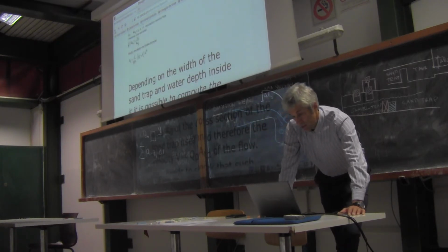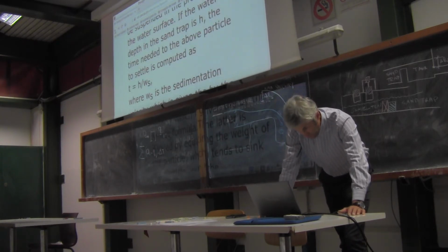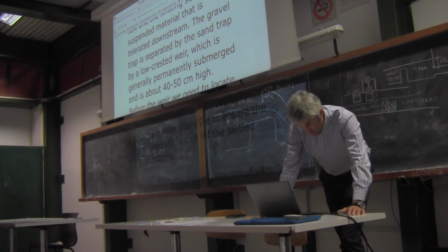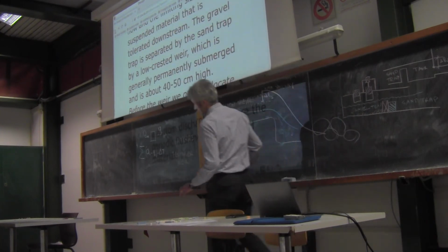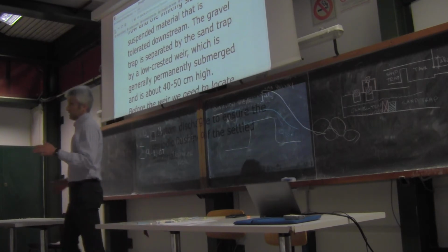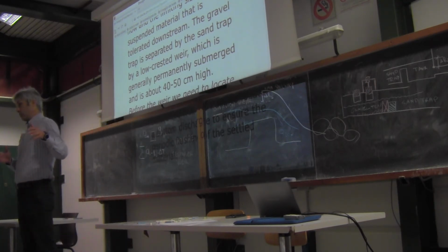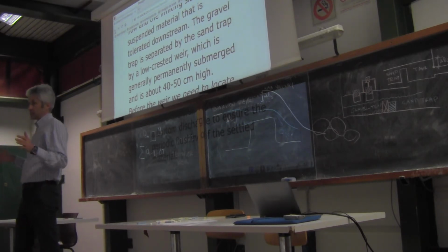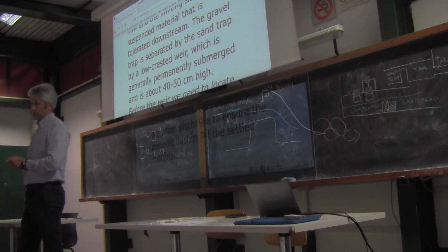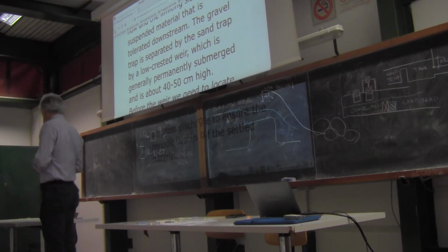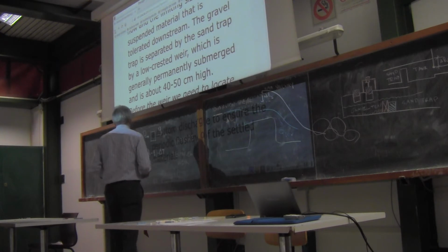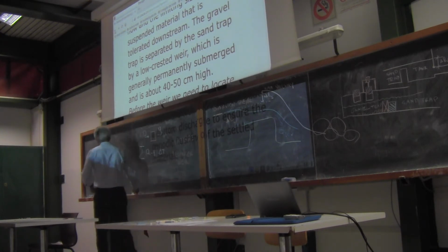And this is why, the reason is that if the water flow is slowed down, the sand trap is more efficient. Okay. And then what we have to design is the width and the length of the sand trap. So basically, what are the relationships that you should use?